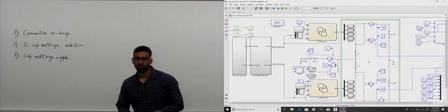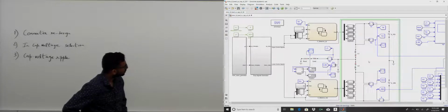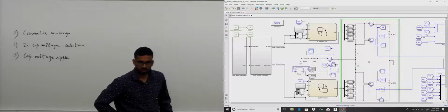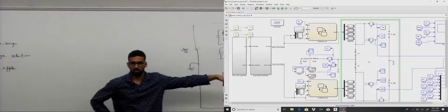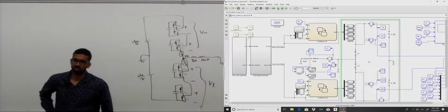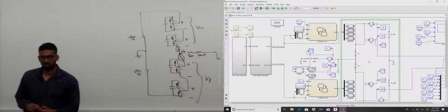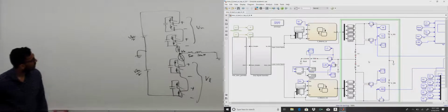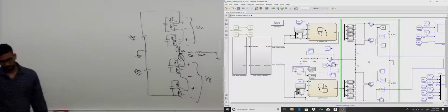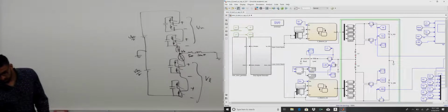Question. I see why we changed the DC bus voltage, and that seems easier than modifying the 50 ohms and 10 millihenries. But could you modify that at all? You can, but this problem is such that the load is not in your hands. You have a fixed load given to you. P and Q are given. So once P and Q are given, the load is given, and that voltage VO is pretty much specified, in terms of magnitude and phase angle.